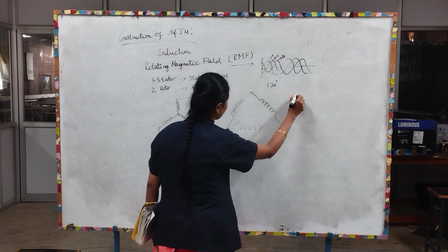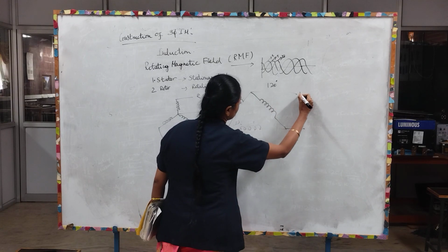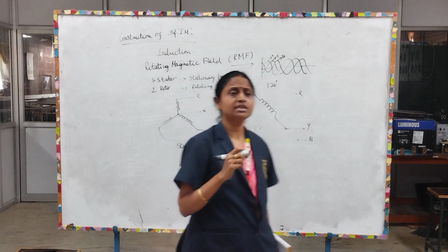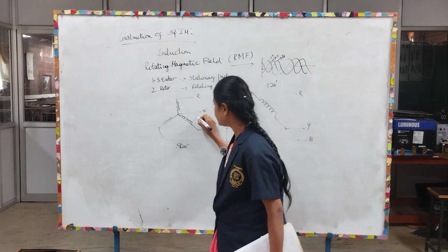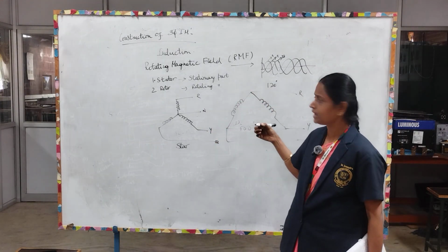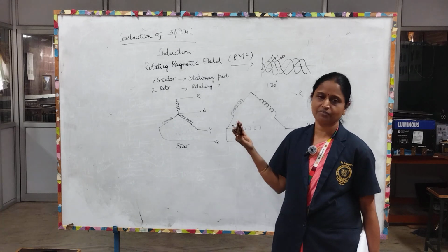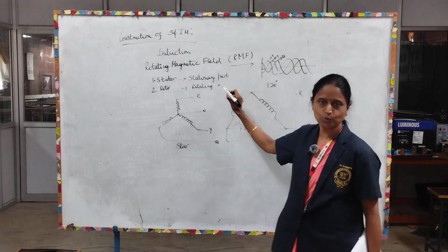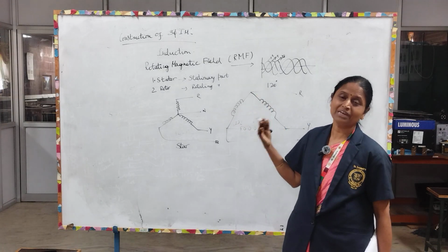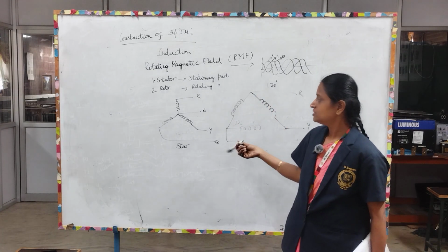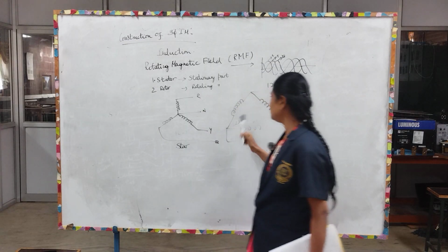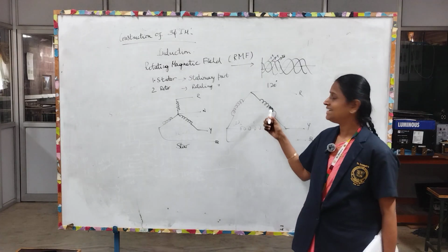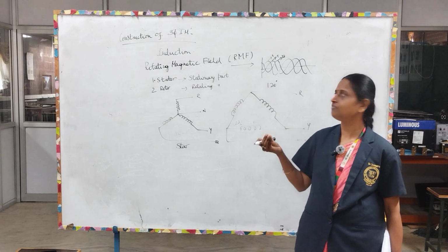Delta is mainly preferred for a three-phase, three-wire system. Star is preferred for a three-phase, four-wire system. So the stator is the stationary part, and the rotor is the rotating part. The stator may be either star connected or delta connected. Delta connected means it looks like a delta, and star means you will have a three-phase, four-wire system, and delta means it will be a three-phase, three-wire system.